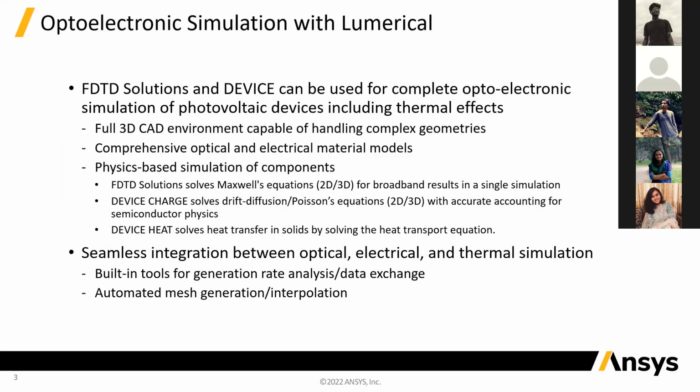With a solar cell simulation, we're doing an optoelectronic simulation, and in order to do that, we have to use multiple solvers. The solvers that we're going to use are going to be FDTD. We used to call our multiphysics solvers DEVICE in general. However, we should now call it the CHARGE solver for the electrical simulation, and the HEAT solver for the thermal simulation. So the three solvers that we're going to use are FDTD, CHARGE, and HEAT.